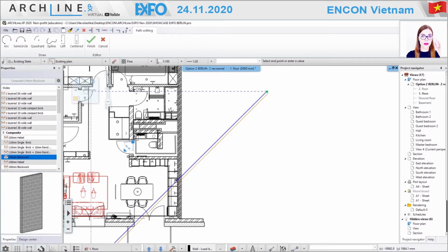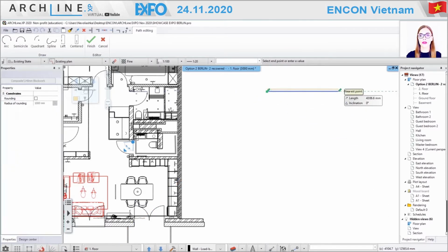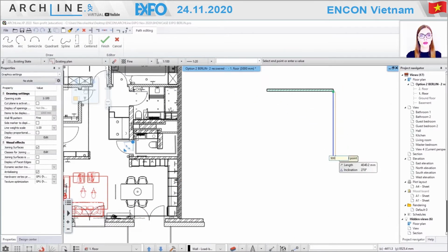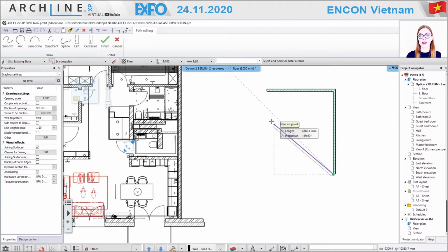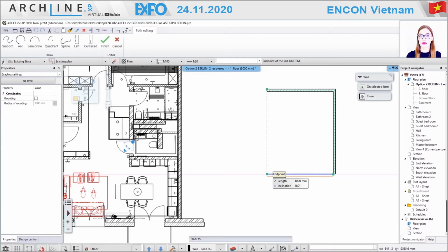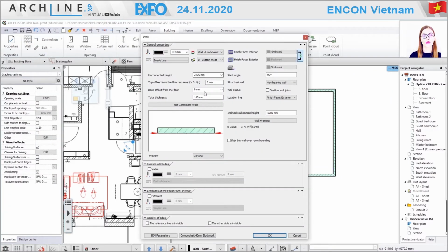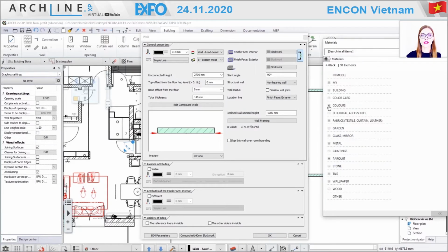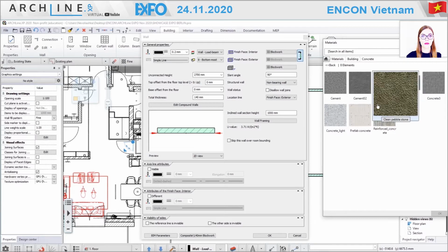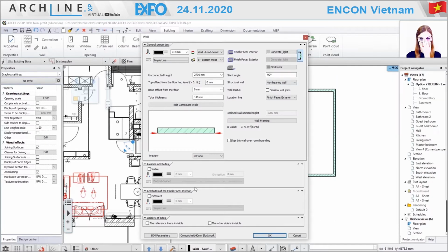So you see that, for example, now we create the walls, and you can choose options and create a spline, or just follow up with a rectangular shape, which is what I'm actually doing. And then you can go on and correct your wall if you're not satisfied with this. It's very easy to do, even on the level of interior design, creating the material you need, or you also can think about documentation, how you will represent it. For example, the outlining or a hatch.